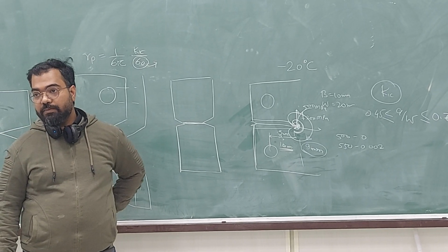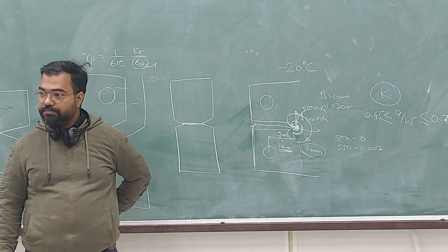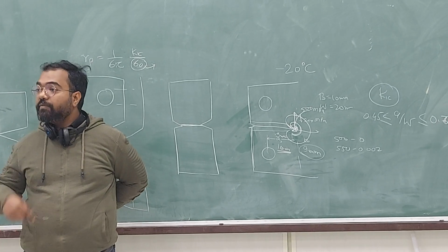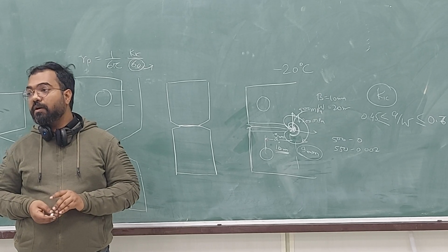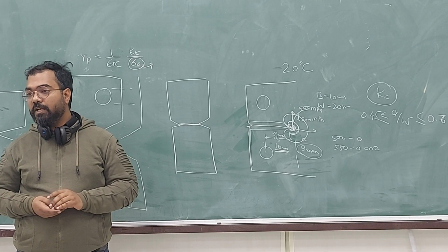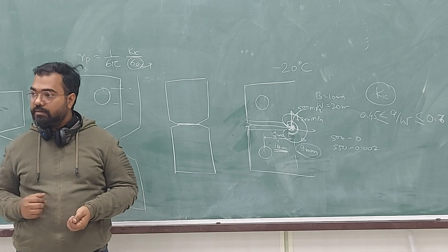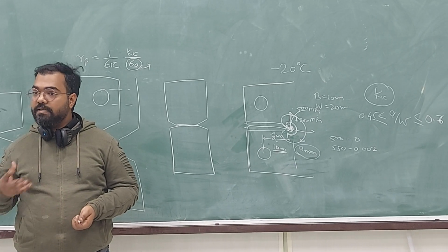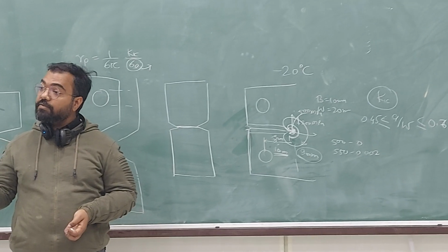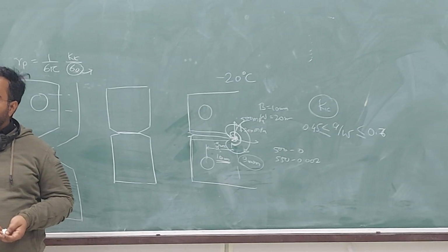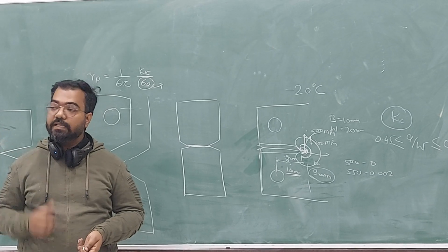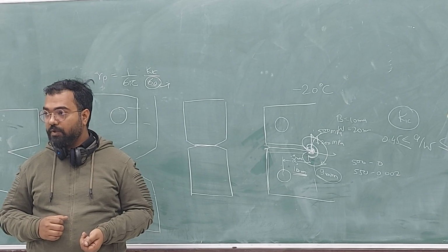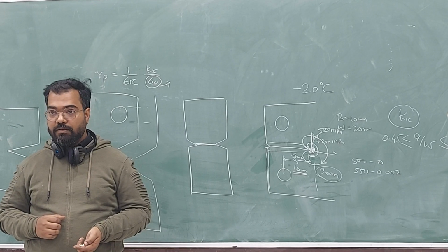Now it has been updated to stress intensity factor. Previously, the standards said that the sigma max you apply must be some fraction of the yield strength of the material. Now they are saying that the stress intensity factor which you apply in fatigue must be smaller than a percentage of the stress intensity factor you achieve in your K1C testing. Okay?